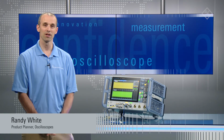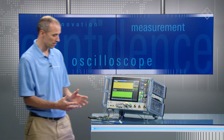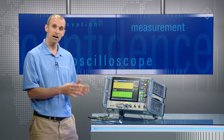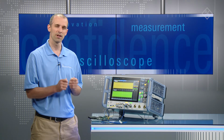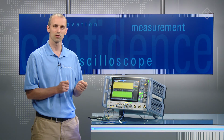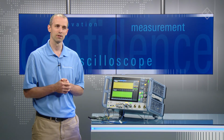Today I'd like to show you an example of de-embedding with a USB 3 signal. Here in this example we have a USB 3 drive connected to a fixture. Out of this fixture we take both the positive and the negative complementary signals and run them through different cables. One cable on the positive side is going through a short 20 centimeter cable. On the negative side it's going through a longer 2-meter cable.